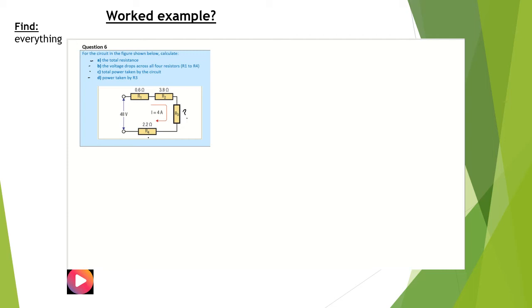So we've got 2 unknowns here. This is the game of chess I talk about. So what we need to do here, I think a fair way to start this problem would be to calculate the voltages across all of these resistors. And when we know that, we can certainly calculate the voltage across this resistor because we know the current through it and we know its resistance value.